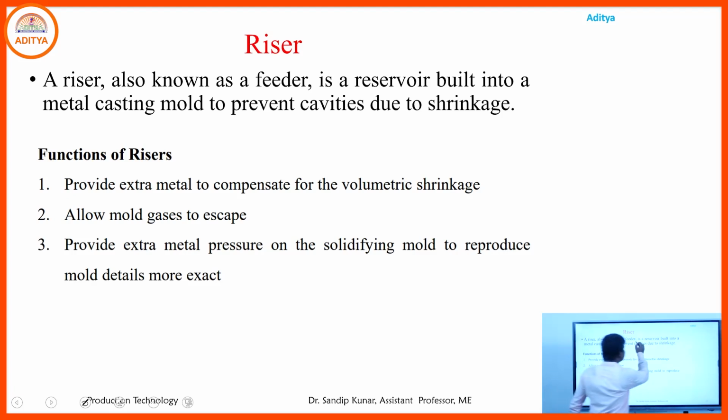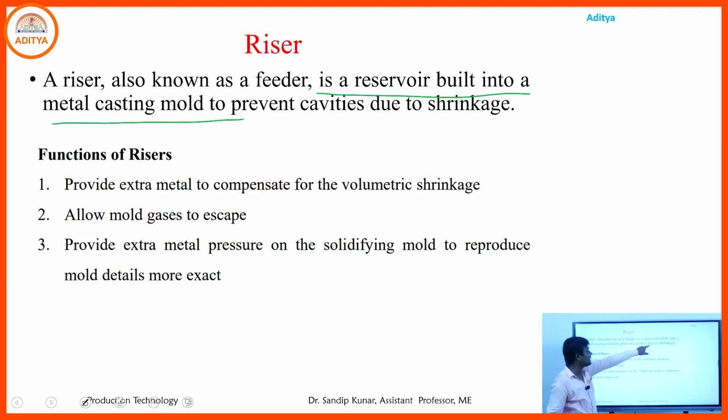It is a reservoir built into a metal casting mold to prevent cavities due to shrinkage. The riser acts as a feeder or reservoir from which the extra metal goes to the mold cavity.